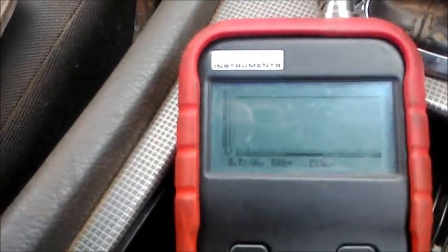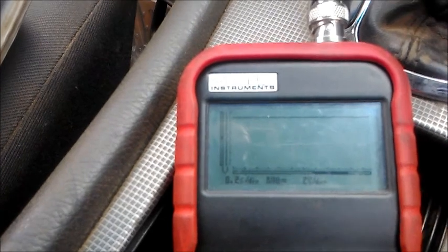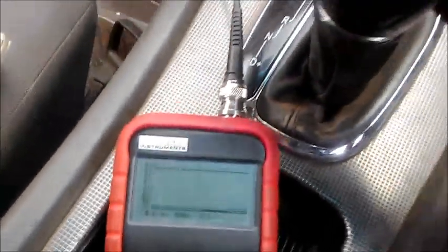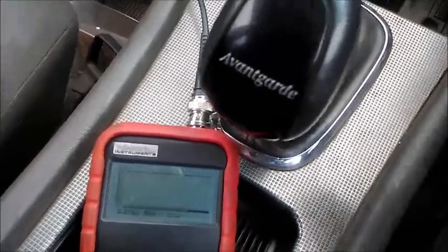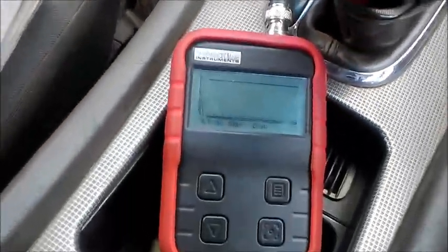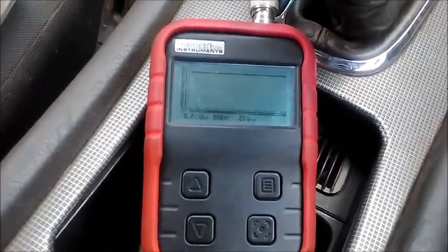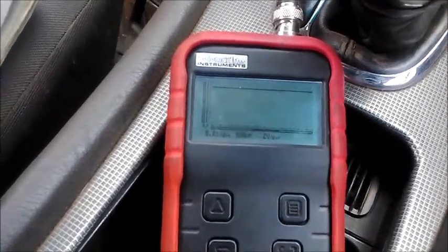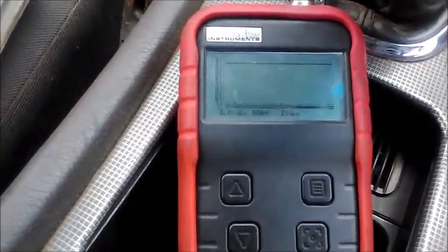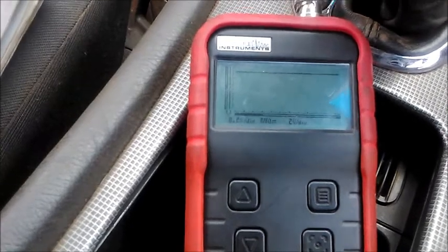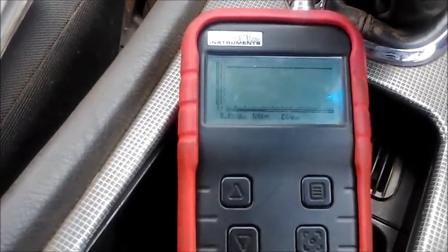Trying to get rid of the glare so you see the signal better. It's a bit difficult because I'm driving at the same time. I'm reversing again. Reverse a short distance. I'm now engaging D. It is now in D, and I'm rolling forward now. Clearly you can see there is no signal on that sensor. The sensor is well and truly dead.